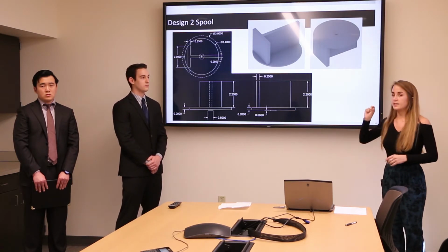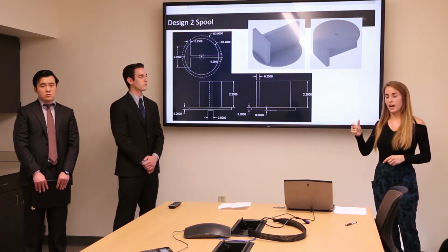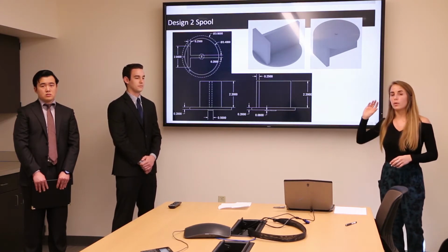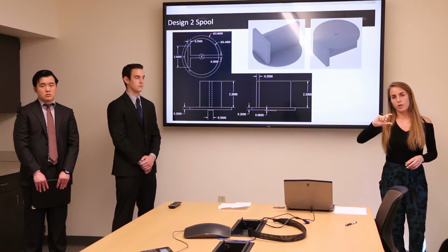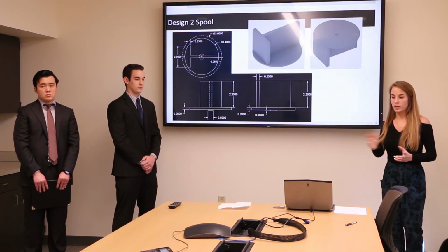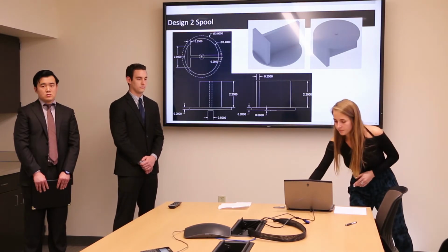So the Y is the same thickness of 0.25 as the housing wall, and it works the same way as the T. It moves back and forth, allowing for both conditions. It's just a lot thinner, which means that we save a lot in cost.